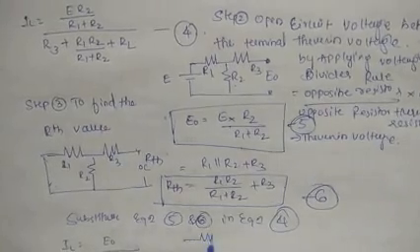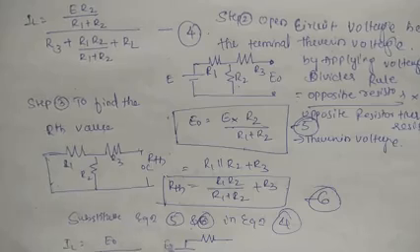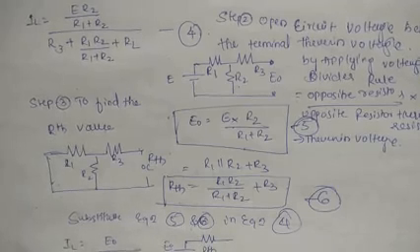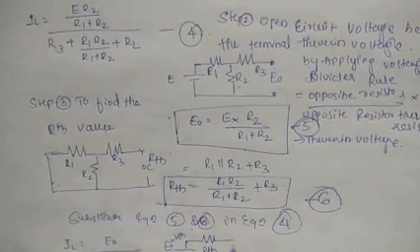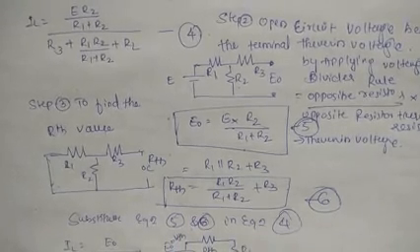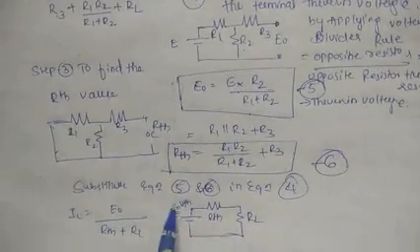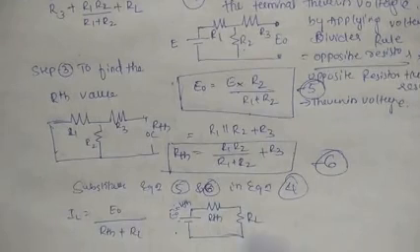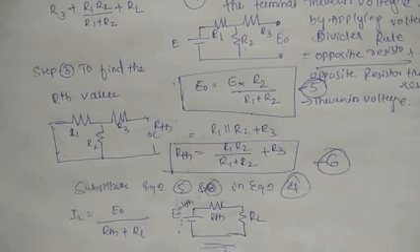This is your Thevenin equivalent circuit. E0 is in series with the Thevenin resistance RTH, with the load resistance RL. We also take E0 as VTH. This is your circuit, E0 equals VTH, we can take that name. This is your proof of the Thevenin theorem.